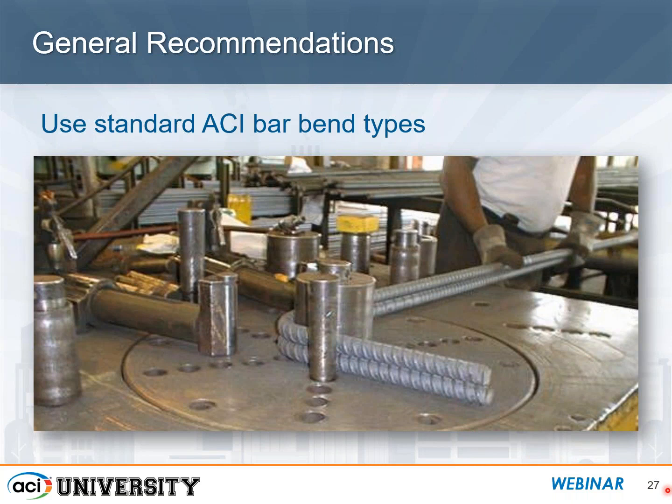It's, in short, a very expensive proposition for really no benefit. You wouldn't want to use anything less than the minimum, but if you were thinking about using something more than a typical standard bar bend, you really get no benefit from it. So we strongly encourage to use just what those values are given in 318.